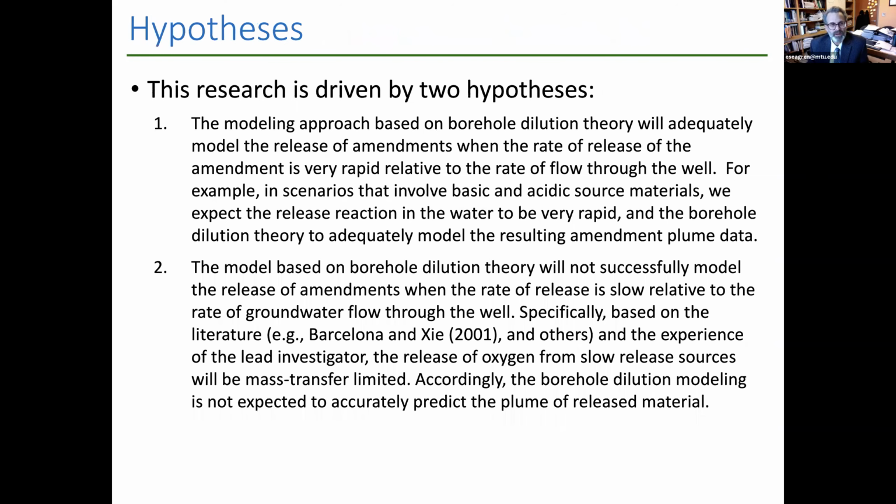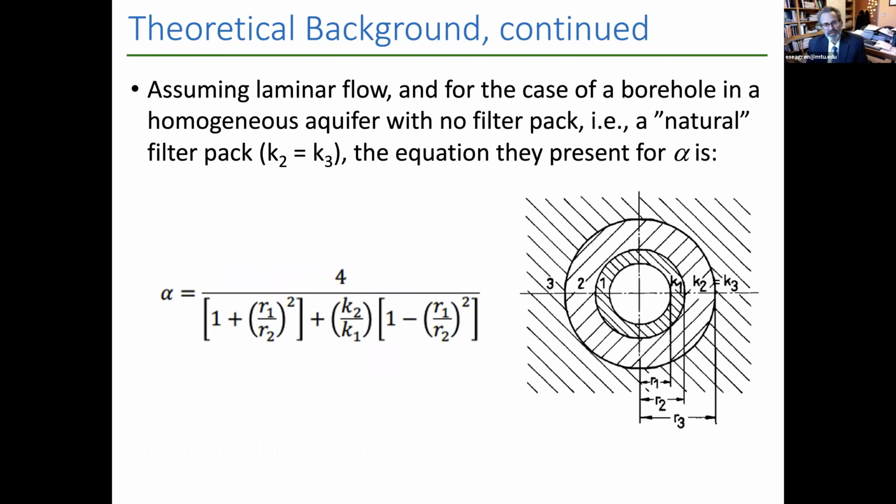Well, let's see, if you just look here, because the flow rate is proportional to the permeability or the hydraulic conductivity, it kind of washes out of these expressions. And so the flow through these different zones is all going to be proportional to their permeability.